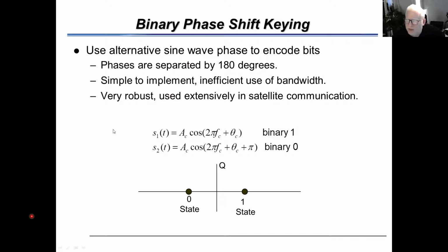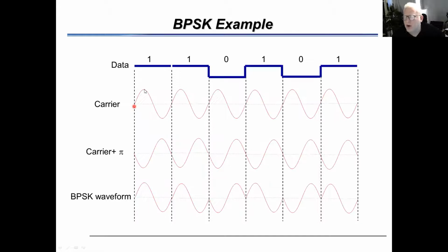This was one of our previous lecture slides. So whenever you implement this on a stream of bits, for example 110101, the ones are represented with a 0 phase, as you can see here in the output. However, whenever you have a 0, it is represented with a 180 phase. So by detecting the phase of the signal at the start of the bit, you can demodulate the output stream of bits, whether it's a 0 or a 1. This is what we call binary phase shift keying.